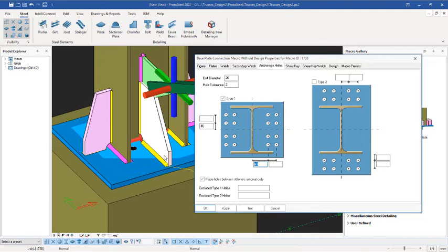So this distance now, I can manage it by pushing the hole outward. For me to do that, I can key in here maybe 60. The same thing I will do on this other side. I will key in 60 right there. Alright, click on apply. You can see the hole has actually come up. So I'm having altogether a total of 4 holes on this base plate. Alright, the bolt diameter is 20 and then the tolerance is 2. Alright, so everything is good now.